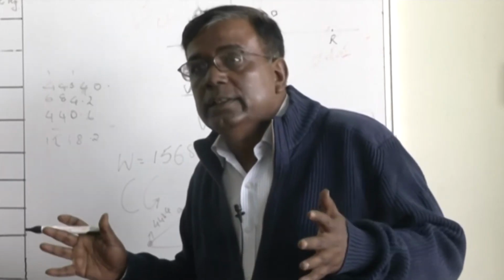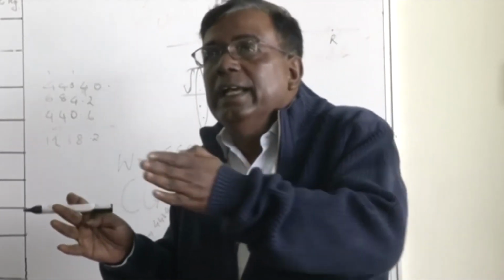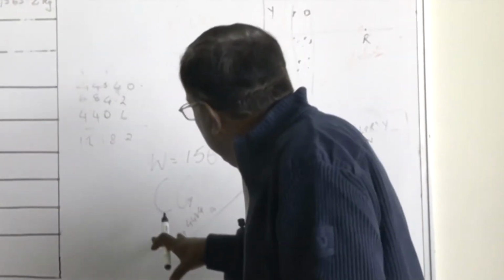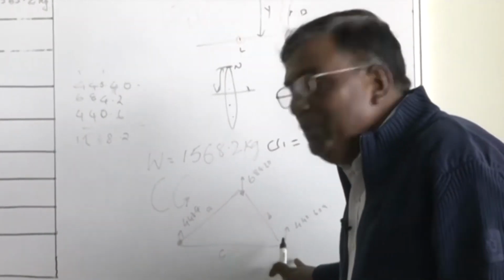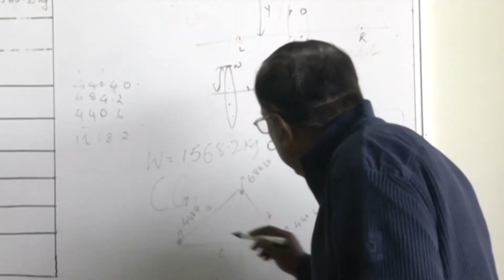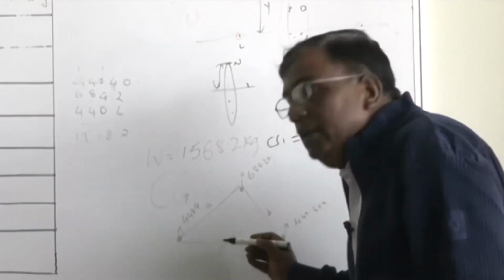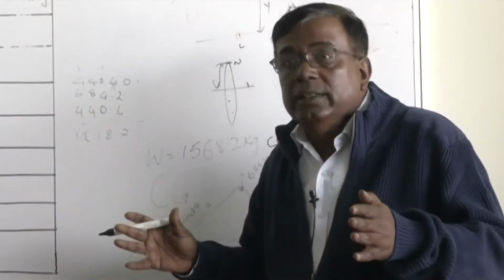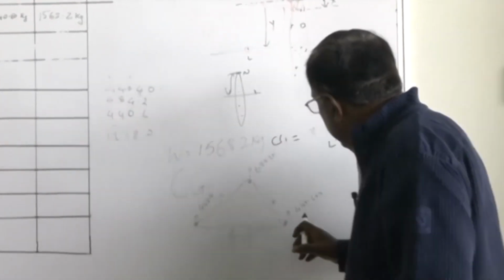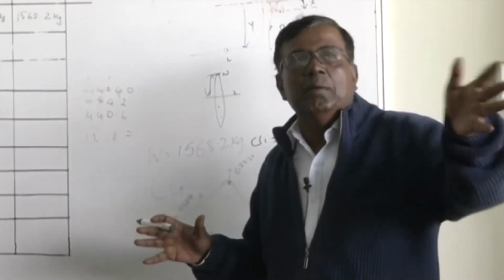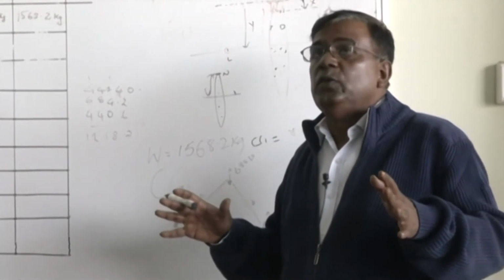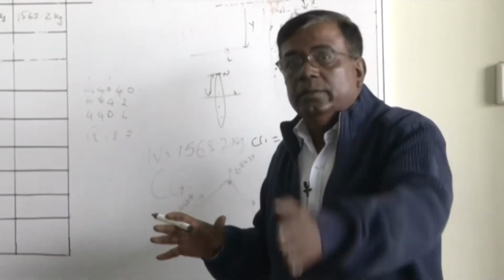That shows what? That shows there will be hardly any lateral shift in the CG. If suppose this weight was much more than this weight, that means CG would not be in the center line. CG will be little towards this weight. But we want as a designer, the CG should be on the central axis. So this number, when you see within this 3 kg difference, there may be so many other small accessories here. So you know one thing, that the aircraft is beautifully designed and CG will be in the center line.